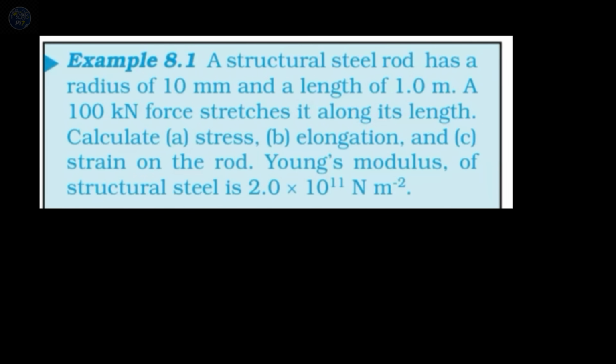Okay, so whenever you see such a question, the first thing you need to identify is what kind of stress the material mentioned in the question is under. Because once you identify that, only then can you use the correct modulus of elasticity. For example, if the material is under longitudinal stress, then you will be using Young's modulus. If it is under shear stress, then you will be using shear modulus. If it is under hydraulic stress, then you will be using bulk modulus.